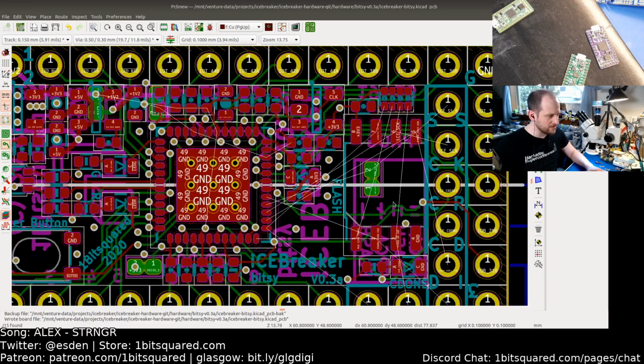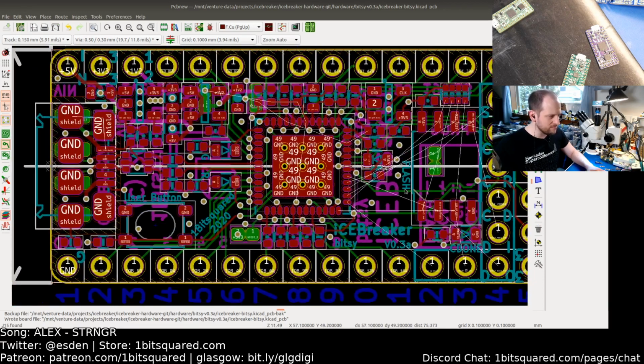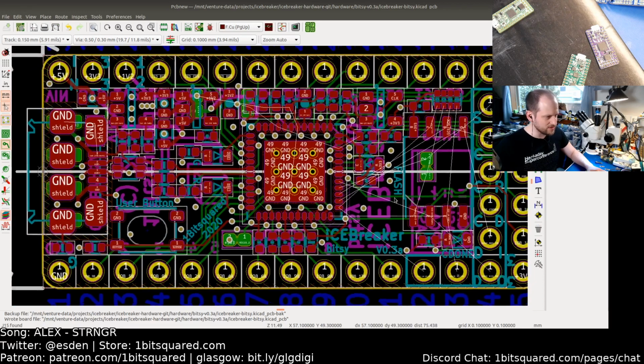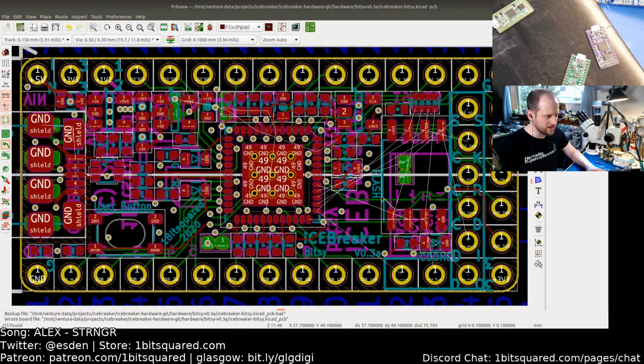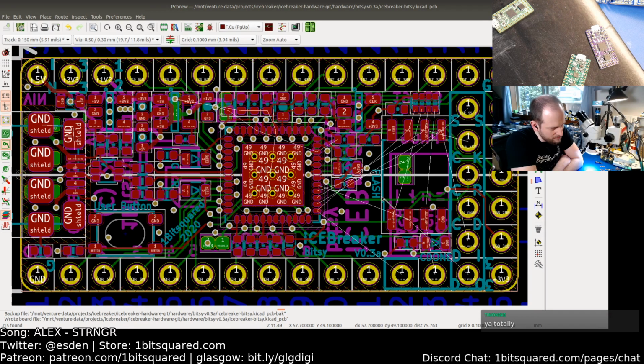But yeah, if there is nothing else that goes, then maybe if it is 1 or 2 signals, there's a reason to do that. But then the board usually is so dense that it might be worth going to a 6-layer to actually clean up the design enough to make it genuinely cleaner and not as crazy. So yeah, 6-layer is still doable.